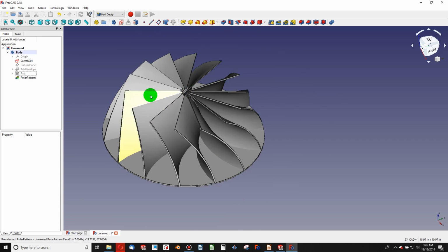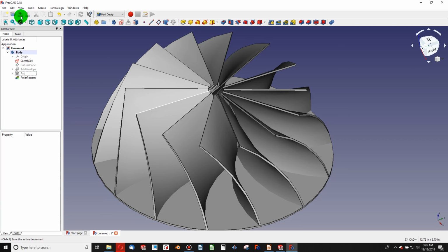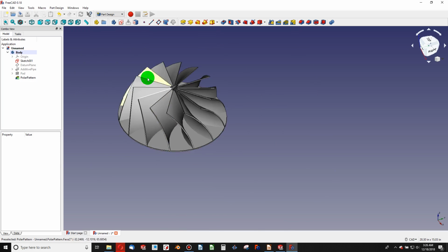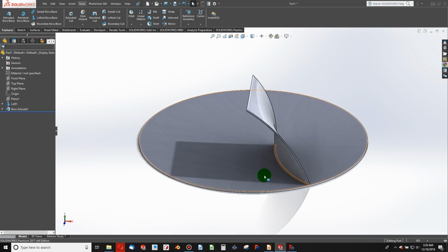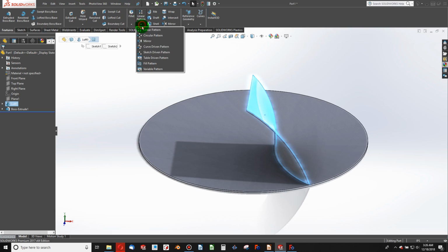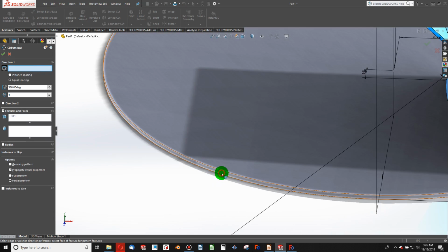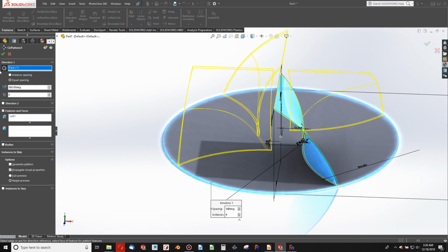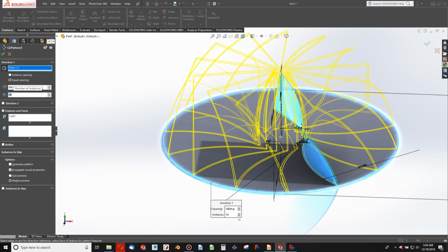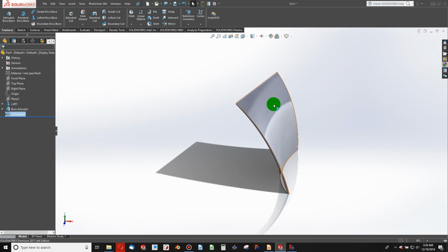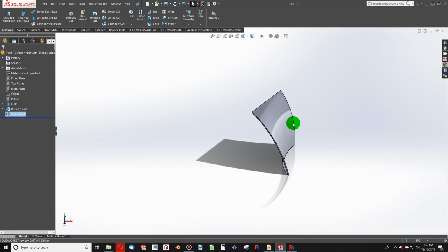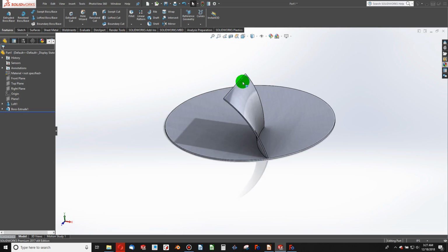And after thinking about it, we've got 14 blades. So that's good. Let me go do that in SolidWorks. Circular pattern, and I just choose a circular face for direction. That's the easiest thing to do. Notice we've already got equal spacing at 360 degrees, so let's add 14 and hit the box. And something went wrong. So if that kind of error occurs, let's try that again.